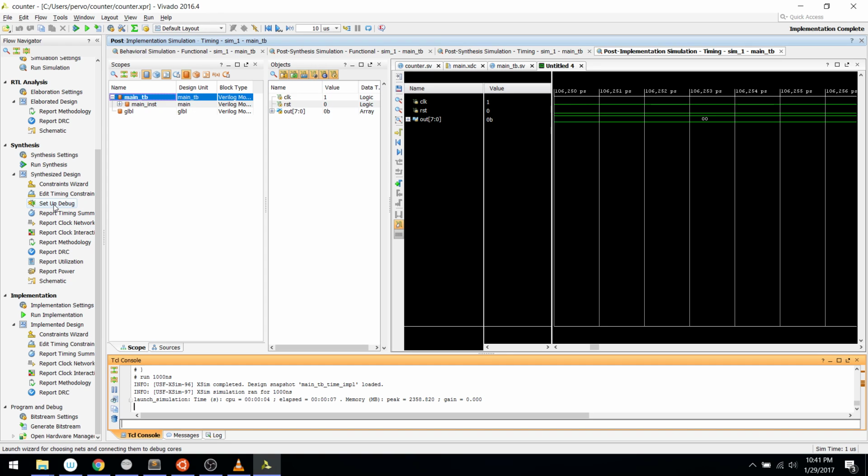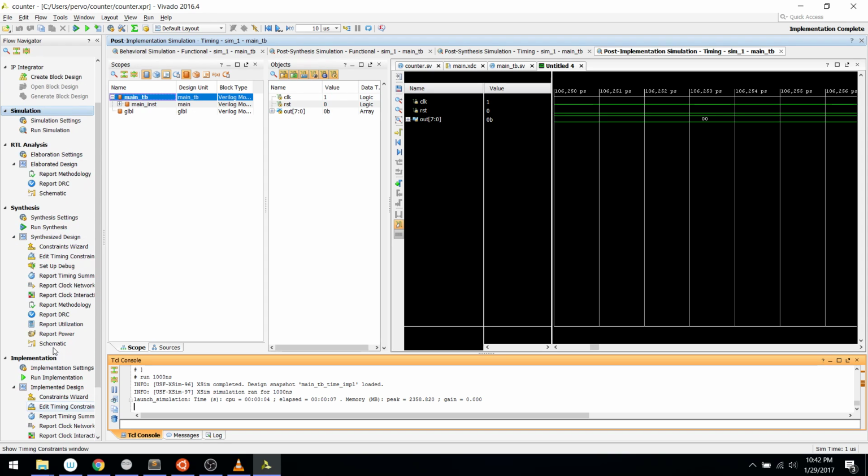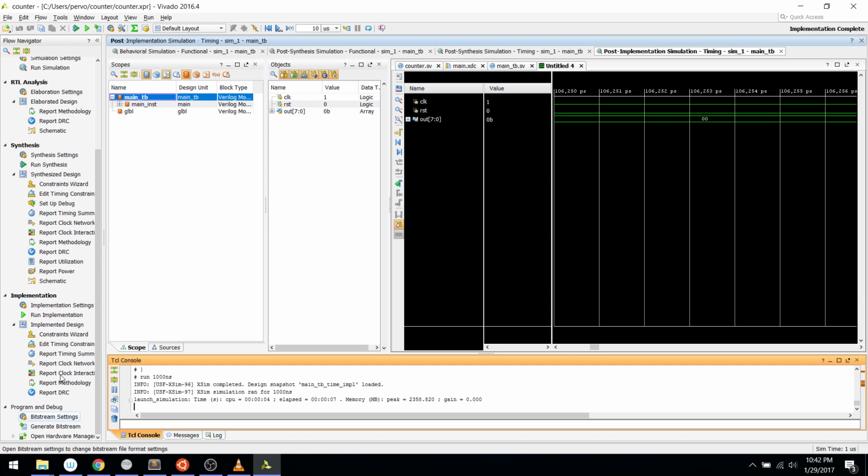In particular, there's a very cool debugging feature when you're running on hardware where it has a sort of virtual logic analyzer, and you can use it to do a lot of cool features reminiscent of software debugging by instantiating actual FPGA code and sampling signals and buffering them and doing triggers and stuff like that. But without a hardware setup, I can't really demonstrate that. But yeah, I think this showed some of the basic stuff.